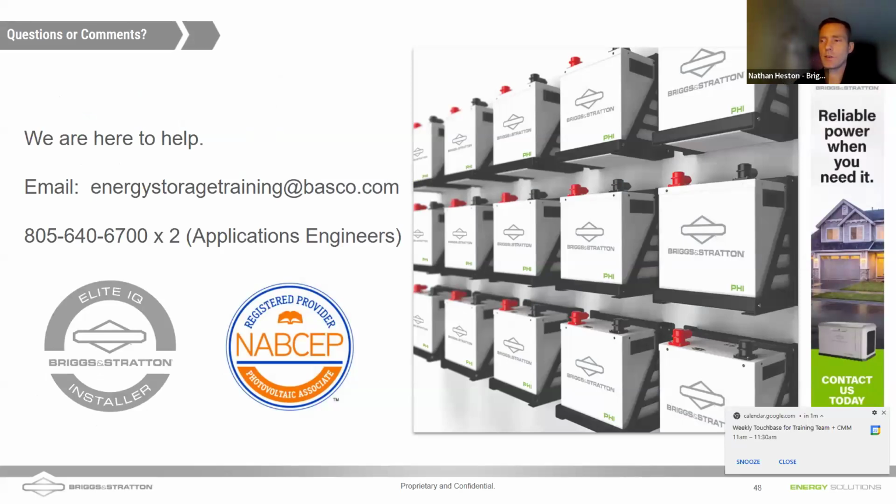So Daniel, let's answer some of these questions. Yeah, let's go quickly back to Andy Malone, who asked about the neutral ground bonding. Andy Renner, who's with us on our team, mentioned the neutral ground bond should be made in the whole house transfer switch in that scenario. That's your first point of disconnect, since it has a service entrance breaker built in. Then the customer's load panel off of that inverter, the solar converter, becomes a sub panel, and you would have to separate the neutrals and grounds there. Additionally, Nathan, on the other subject, you just press the manual button. There's no need to hold it down.